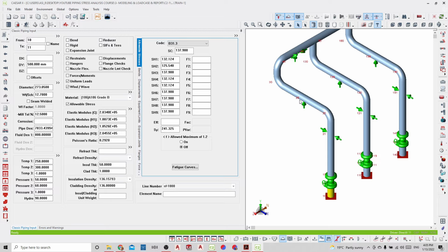To give the right calculation, in this case you need to remove the support. So if we need to do this the right way and have the right sustained effect of the supports on the model, you need to run this analysis, and every time you have a non-linear support, you need to remove this support. That's what we were doing before: once we have an uplift support, we remove it.